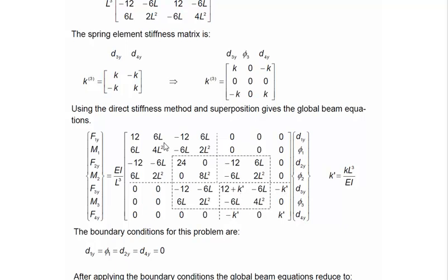All right. So if we look at the overall assembly of the global stiffness matrix, how much is the global degree of freedom of the system? We have 7 rows and 7 columns, so the global degree of freedom is 7 by 7. And how are these labeled? The first one is D1y, then phi 1, D2y, phi 2, and D3y, phi 3, and D4y.